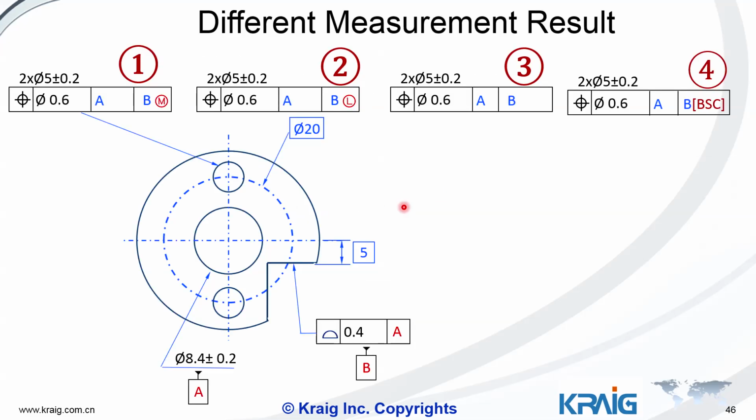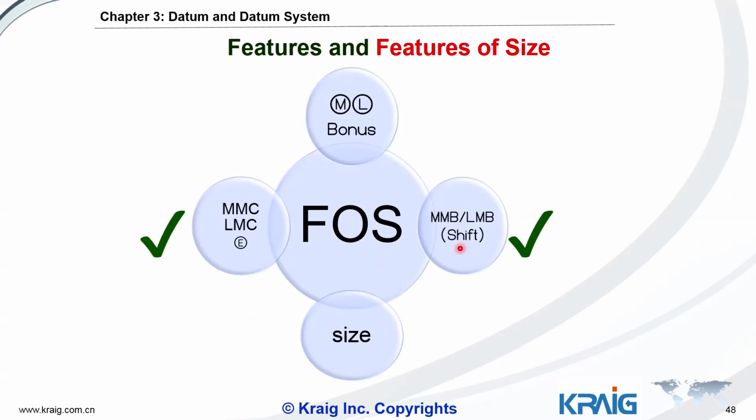You see, the previous example, the datum B is a surface, but datum B is the secondary datum, not first. Okay, in that case we can find the maximum material boundary and the least material boundary, reference to the previous one, datum. Okay, all right.